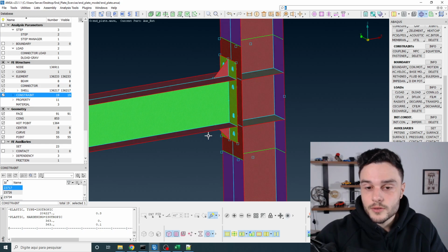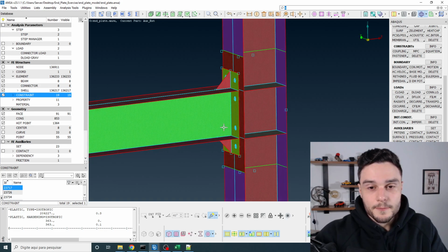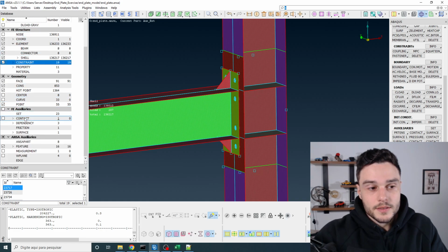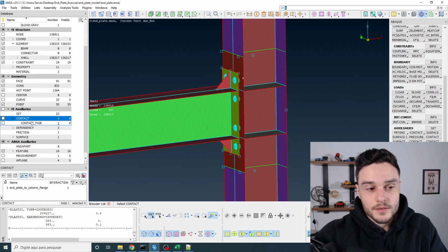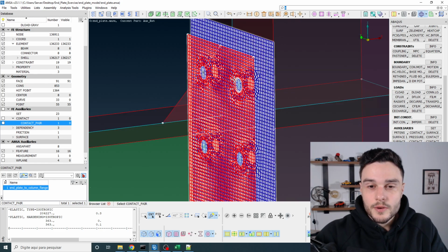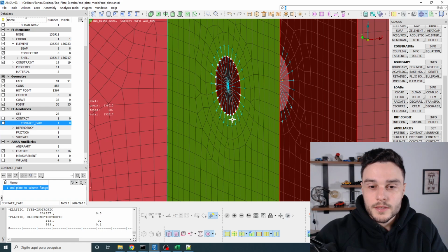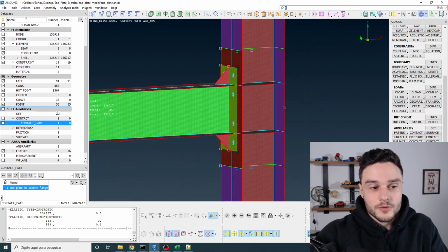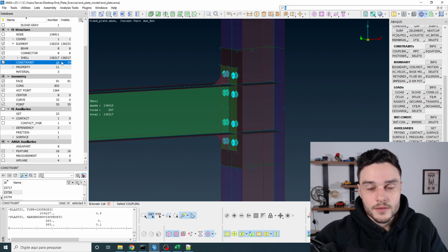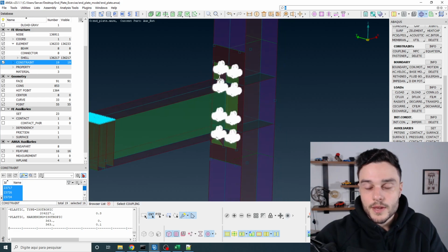I usually follow. Let me see how much time we have. Well, not so much time. Okay, so let's search for contact, expand, double click on contact pair, and then we have this contact defined, right? I want to remove from the slave surface, the red one, the elements that are related to these nodes that we have the coupling. So to do this, double click on constraint, create a box selection using the left mouse button to select all these couplings that we have here.